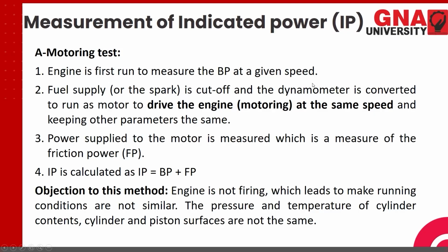Now there are some objections to this method because the engine is not firing, which leads to running conditions that are not similar to what they will be when the engine is running, because higher temperatures are encountered during combustion. The pressure and temperature of the cylinder contents, and cylinder and piston surfaces, are not the same.